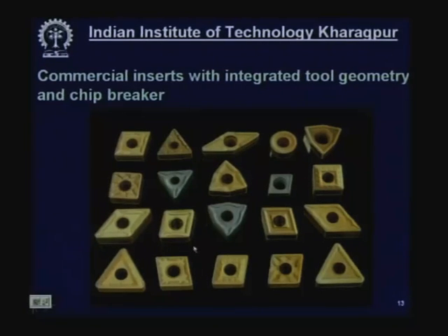In the compaction process, the tool by which the compacting is done before sintering is given this typical shape by electro discharge machine, electrochemical machine, which was not available earlier, but nowadays these are available, and the design part can be very comfortably and quickly done with the help of computer aided design. So, with the advent of computer aided design and these processes like EDM and ECM and the easy compaction and sintering, such kind of very difficult patterns to give the integrated chip tool geometry has been possible, and now these are very popular and widely used.